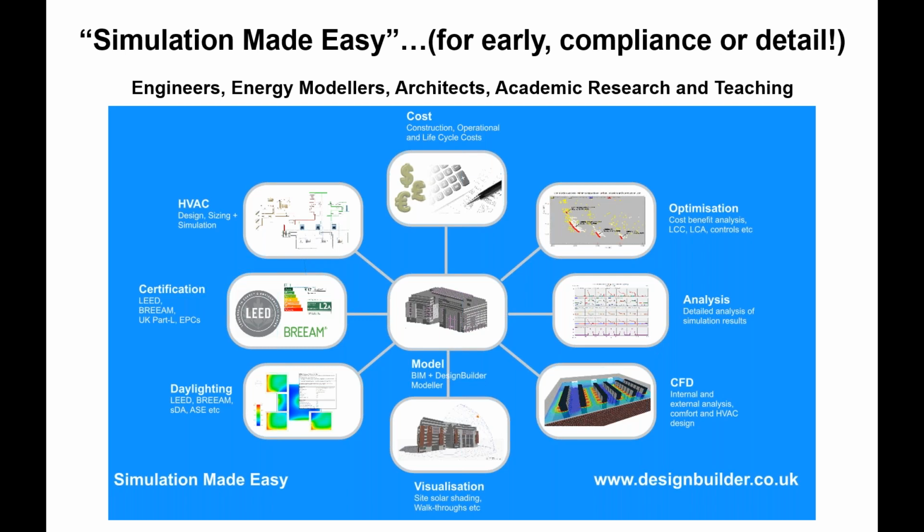We also use the Energy Plus engine to run the DSM UK certification calculations and other calculations like the TM52, TM59 overheating analyses, which aren't so heavily constrained by the UK National Calculation Methodology, or the NCM.